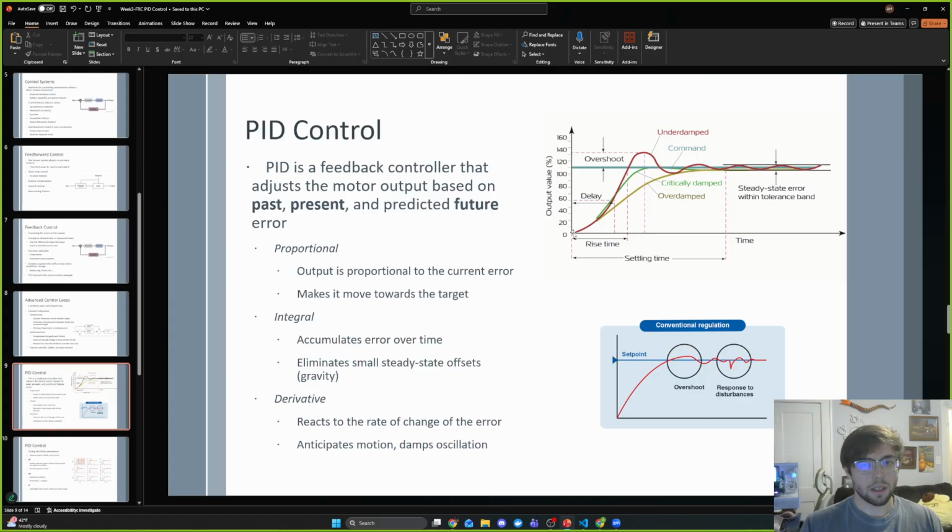What this means is you move quickly towards your target position, but you overshoot, and so your system tries to self-correct and overshoots again and again, and so on and so forth. This yellow line represents a proportional value that's a little too low, and so it will eventually get there maybe, but it's not optimal, right?